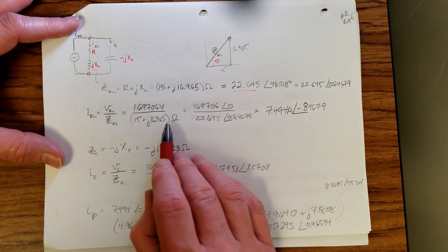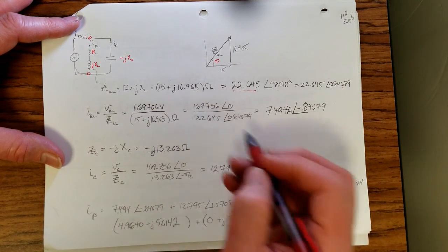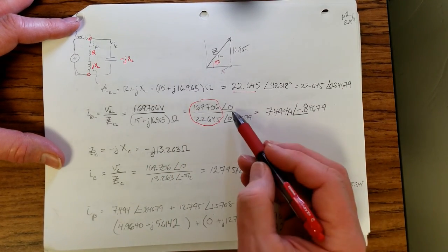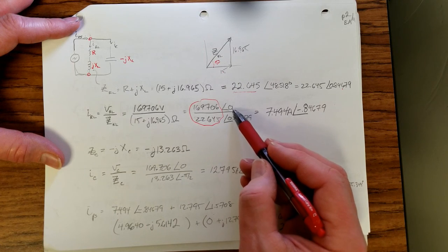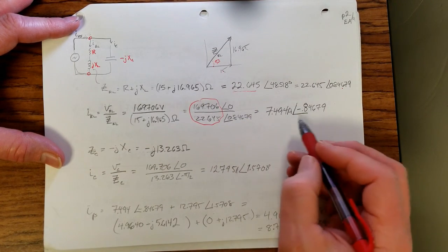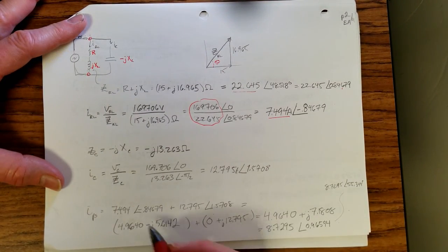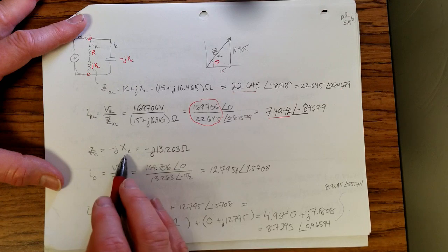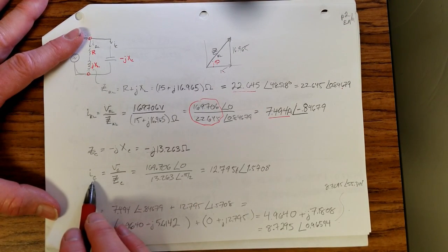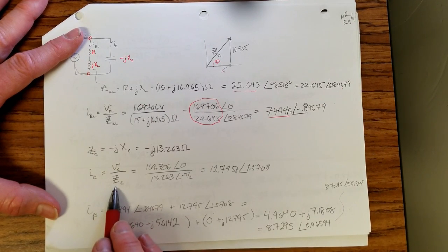Doing the math from polar form, first I put this in polar form, and so my front piece is just that simple division problem, and then I'm dividing, well, with polar form, it's that minus that, so it's negative 0.8679 with a magnitude of 7.494 amps. Z sub C, negative jX sub C, and so as seen on the other page. And so the current flowing down this branch is just V sub C over Z sub C.